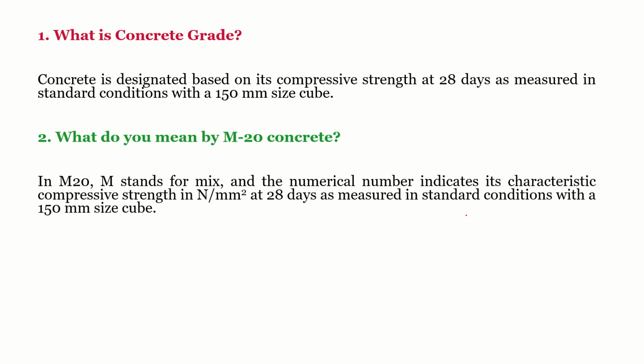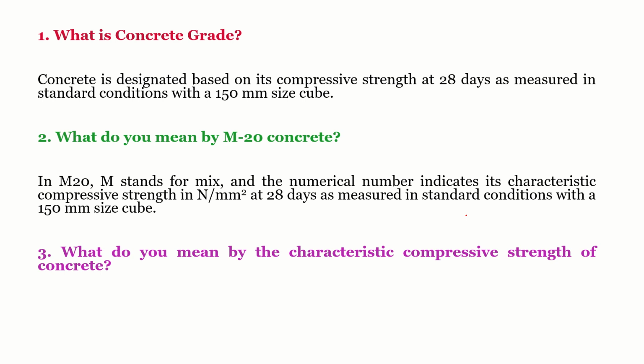Then there's something called characteristic compressive strength. So what is characteristic compressive strength? When people work on RCC, you have something called FCK. Even when we are doing concrete mix design, we use the term FCK. FCK is the characteristic compressive strength.